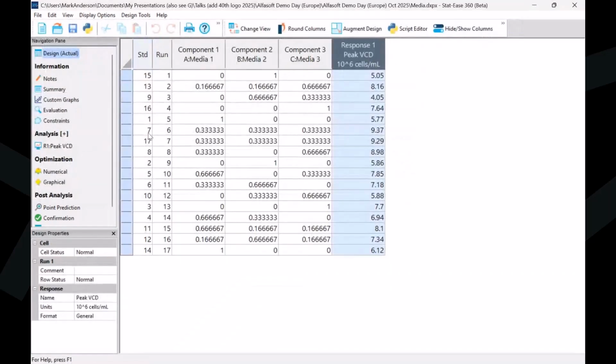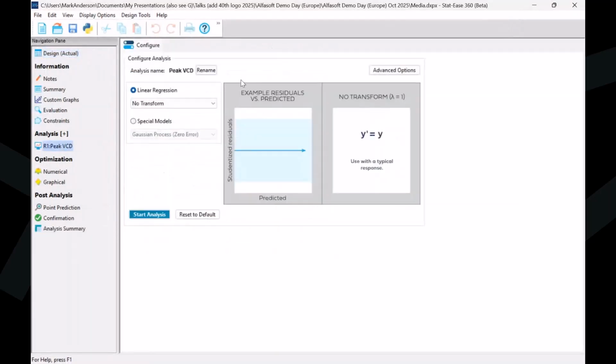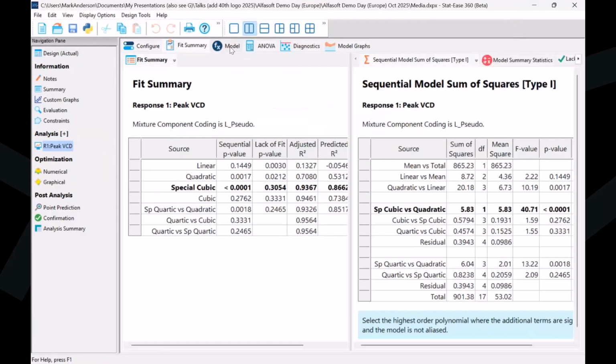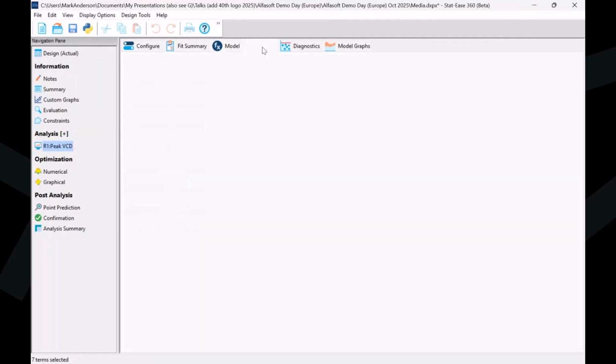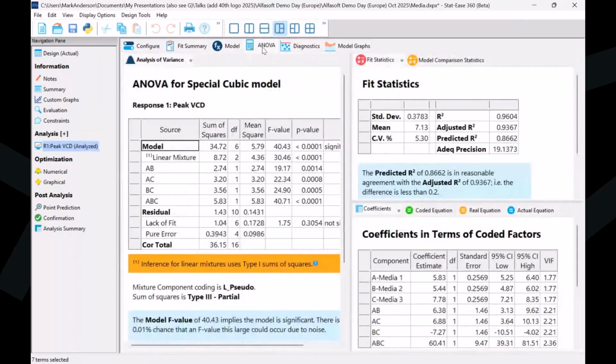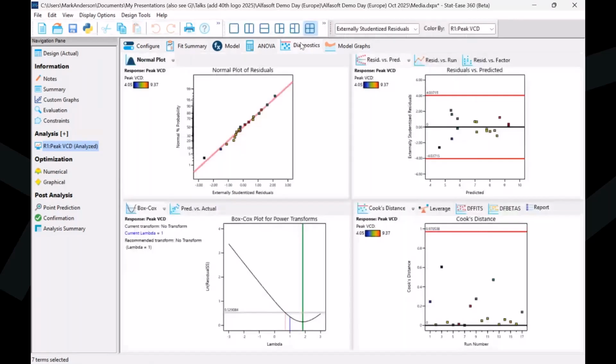collect the results, and then we're going to fit a specialized polynomial model. And basically this is similar to response surface methods, but the model looks different. It doesn't have an intercept, it doesn't have squared terms. So you need to study that a little bit to see how it works, but it actually is geared very nicely to mixtures. So if you're working with a formulation, I highly recommend using Stat-Ease software and using mixture design and making sure that nothing is abnormal via the diagnostics.